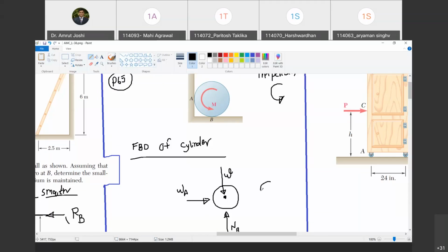As the direction of impending motion is this way, I am going to station the observer on the floor and on the wall. Are you with me? Yes, sir. As this sphere moves in this direction, the frictional resistances must be offered in tangential directions at these two locations and in this fashion. Do you agree with me? Yes, sir.